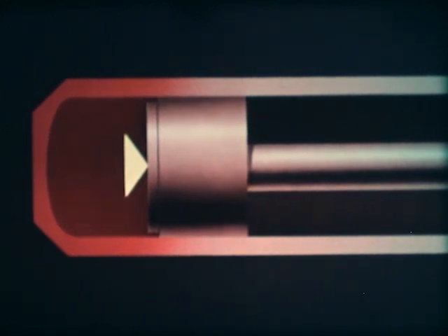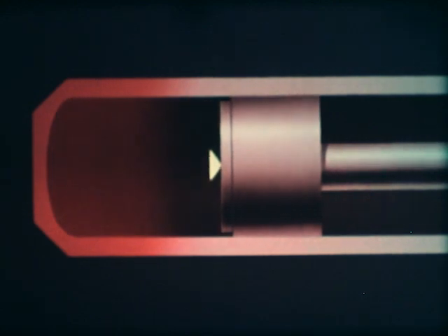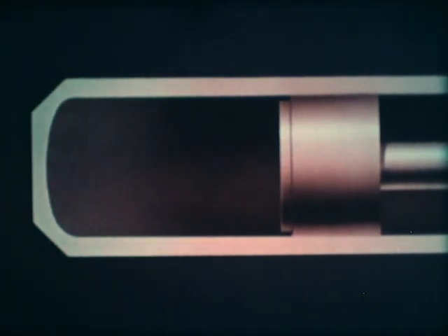Now let the piston be released. It is driven by the expanding gas until the pressure to the left of the piston reverts to 1 atmosphere. If the cylinder head is cooled, the pressure of the gas decreases further. A force is now exerted on the piston in this direction, a force which drives the piston back to its original position.